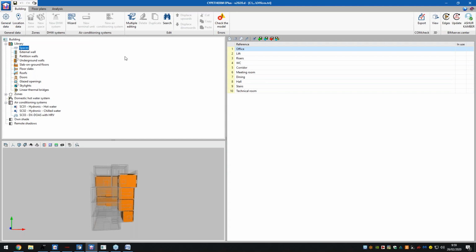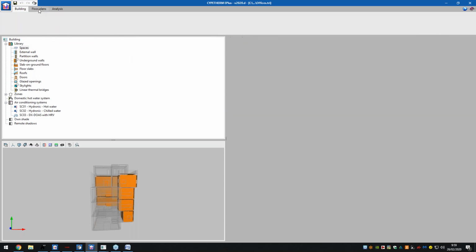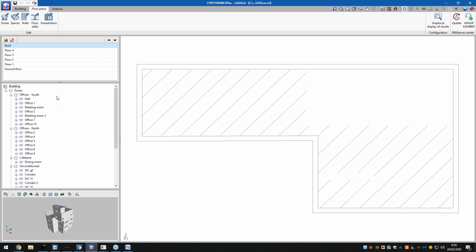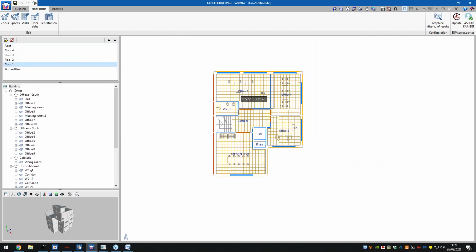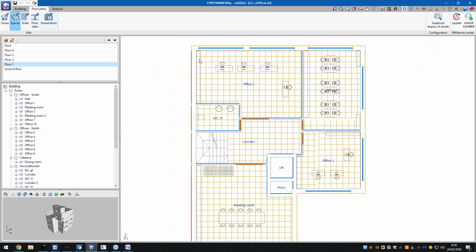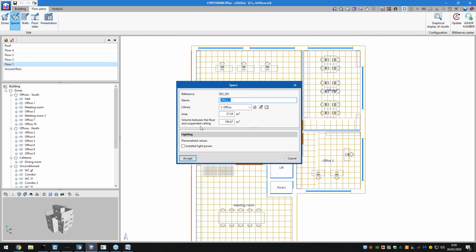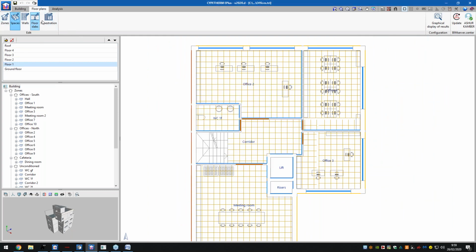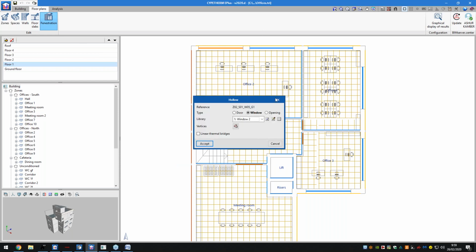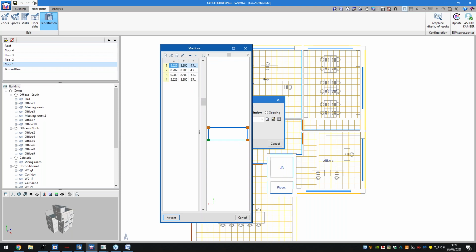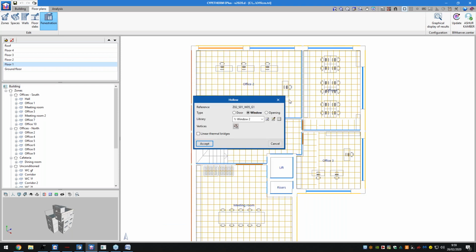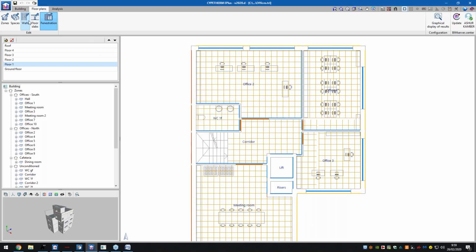It's handled within our HVAC and our Open BIM systems. Now, once we've defined this, we can go into floor plans and get a 2D view of our project. And here, I'm able to define and change certain spaces, lighting specifications, fenestration details for our windows, etc. Look at our vertices for those particular sections, make amendments to those as well, and the list goes on.